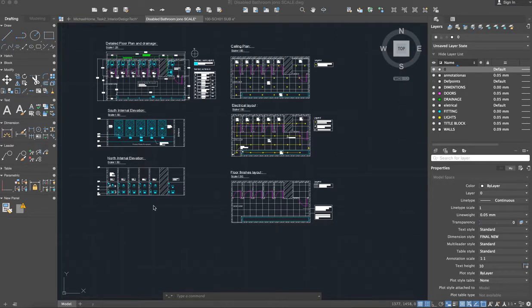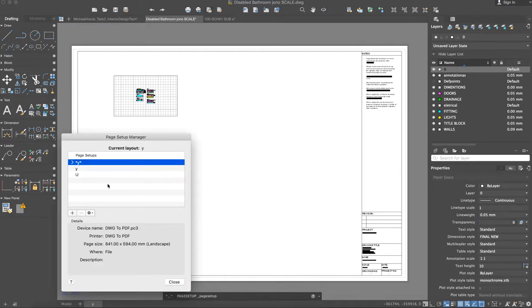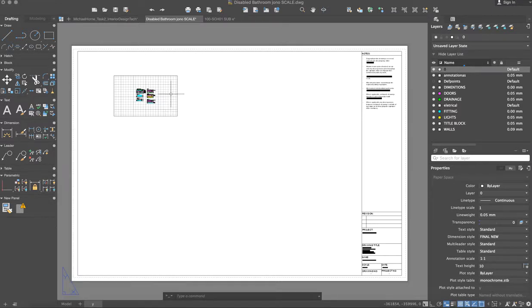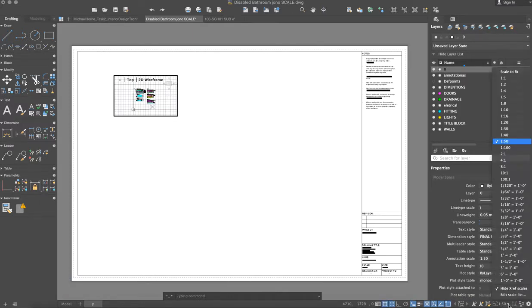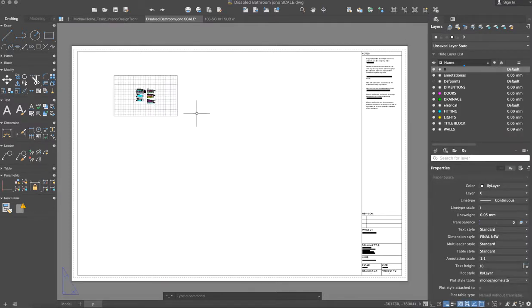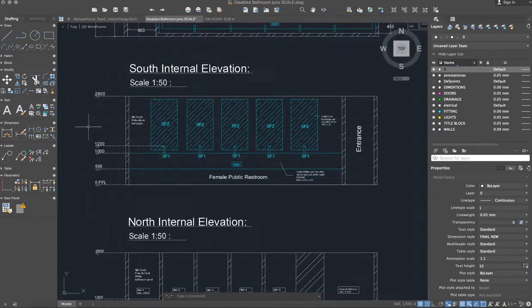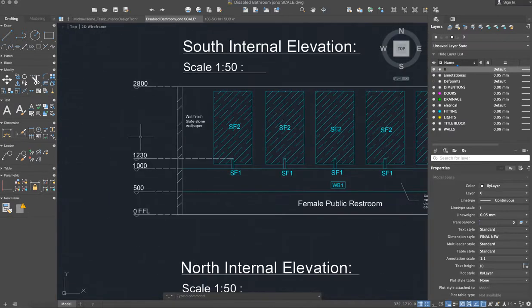I'm just going to see, this is your file that I've opened. I want to check what's going on with your scaling. You say in your title block here, okay, this is Y, because that's an A1 page. That's your viewport scale, 1:50. Okay, that looks right, 1:100 even smaller. 1:50 should be quite big. So there's something wrong there. It's not the annotative. Okay, let's go check here. This is 1:1. If that's all scaled correctly, the thing I'll check is the actual dimensions of things.